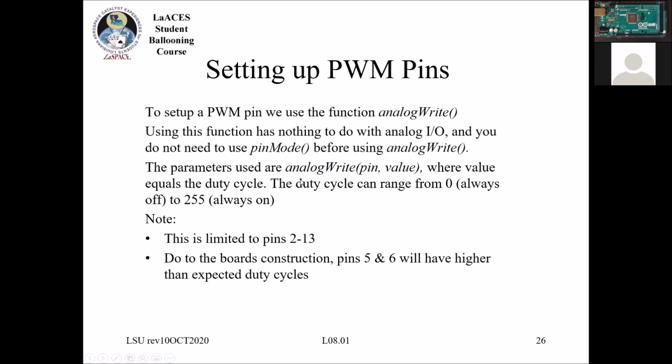But in this case, because you have a variable width, you can go from 0 to 255, where 0 is off the entire time, and 255 is always on. And each individual step from 1 to 255 is going to increment by the appropriate percentage. Like I said, basically you can only use it on the designated pins. And that is it for today's lecture.